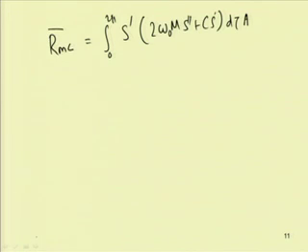So, the solution process begins with a guess solution and the nonlinear frequency amplitude response curve is obtained by solving point by point, by incrementing either the frequency or the amplitude, or one can increment both the amplitude and the frequency. In this case one may use this Newton-Raphson iterative method to solve this equation.